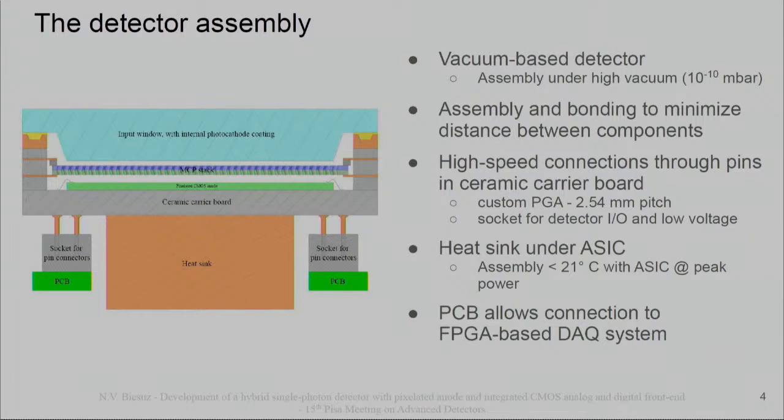The distance here is limited by the wire bonds. Basically, here you have 100 micrometers at least for the wire bonds, plus whatever distance you need to have proper insulation on these. Okay, so this is regarding the voltages.